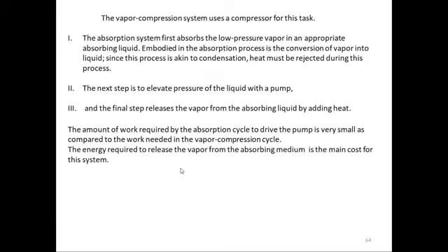So when your absorber has absorbed your salt, then to release it back, I'll show you the process how it does it. You have to supply the heat energy. So supplying that heat energy is the actual cost of this vapor absorption system, the actual operating cost. This is done in what is called the generator. In the generator you have to supply the heat.